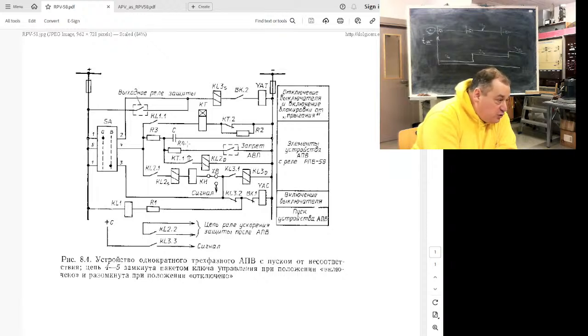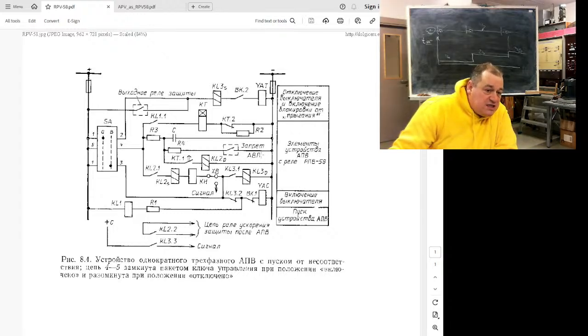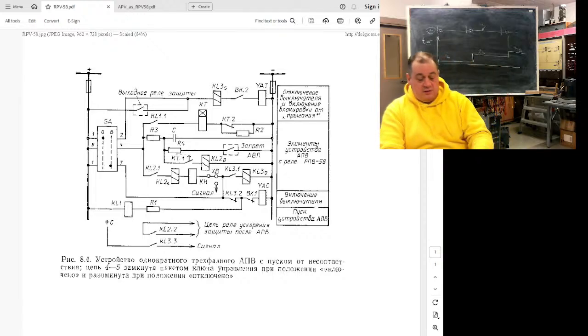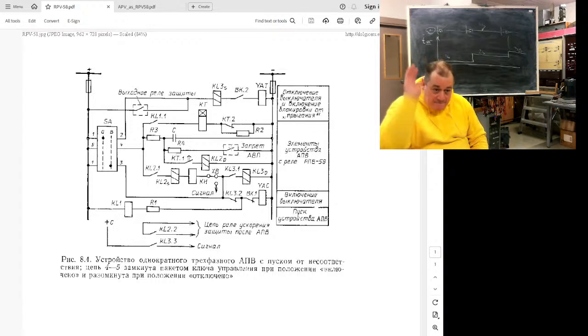If we have switch on fault, immediate disconnect, this capacitor will be discharged, but this circuit, it's an inhibit. In case of, for example, insufficient pressure or over temperature, switch overheat, this circuit can be used as inhibit. There will be no auto reclosing if you activate this button, contact.